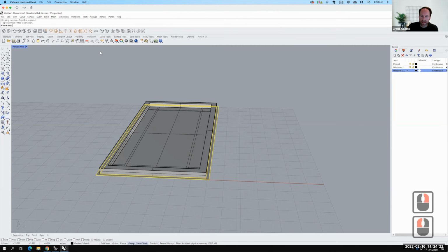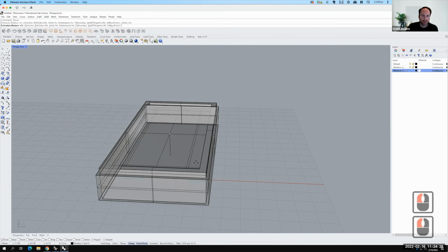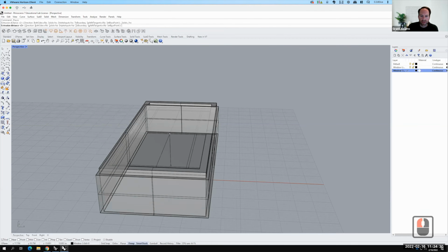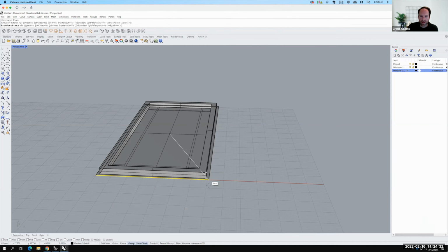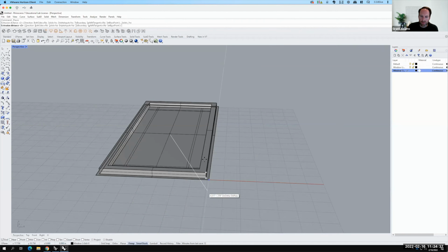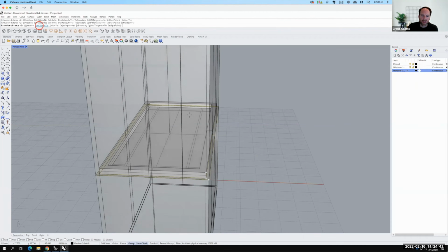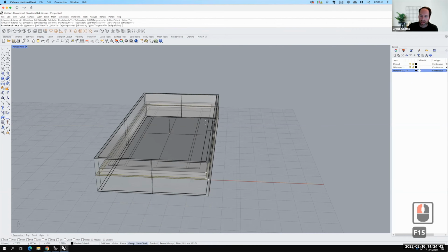Let's take this piece and do the same thing. I'll go up to Solid and I'll extrude surface straight. And now this time, I really would like it to be thicker. And I think maybe it would be helpful if it went both up and down at the same time. So I'm going to go ahead and turn on both sides. And that means it's extruding both directions from the middle.